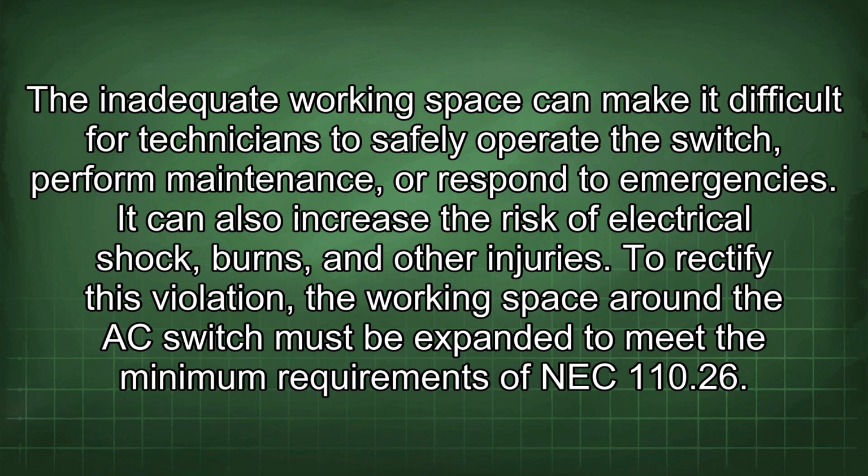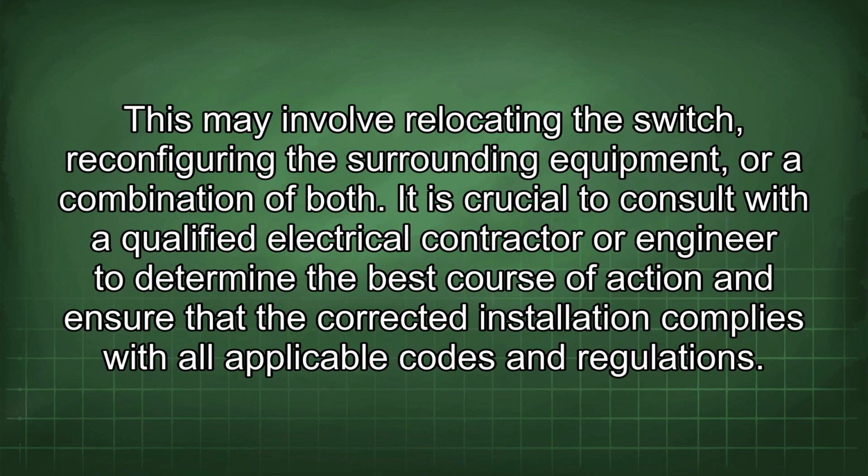The inadequate working space can make it difficult for technicians to safely operate the switch, perform maintenance, or respond to emergencies. It can also increase the risk of electrical shock, burns, and other injuries. To rectify this violation, the working space around the AC switch must be expanded to meet the minimum requirements of NEC 110.26. This may involve relocating the switch, reconfiguring the surrounding equipment, or a combination of both. It is crucial to consult with a qualified electrical contractor or engineer to determine the best course of action and ensure that the corrected installation complies with all applicable codes and regulations.